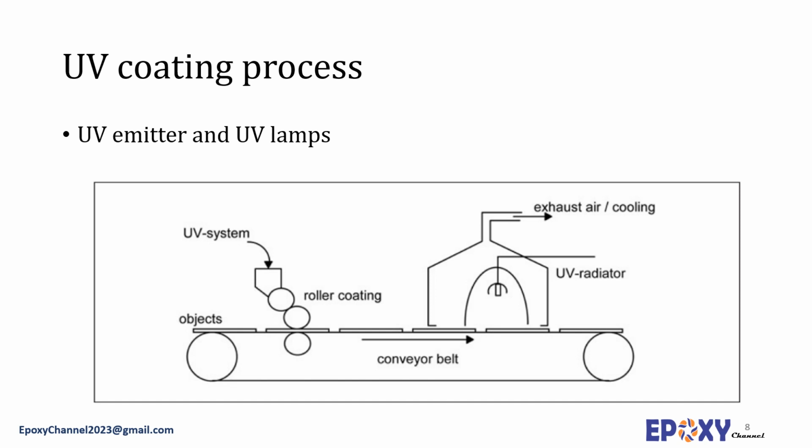A schematic diagram of the typical equipment is presented here. The UV emitter is the most important part of a UV curing process and is the energy source of the UV light. The UV can be generated in a wavelength range of 200 to 760 nanometers by high pressure and medium pressure mercury lamps, microwave UV radiators, electrode vapor lamps, pulse xenon lamps, or lasers.